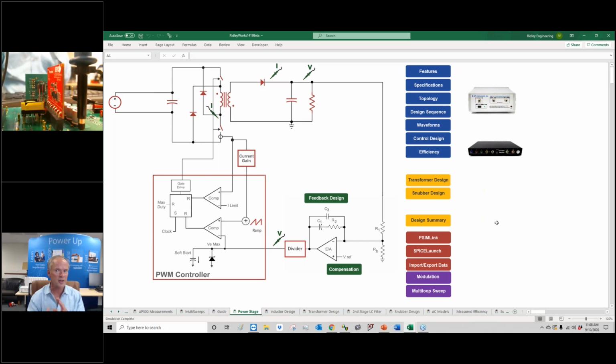All the things we've done on proximity loss, that was originally done for 60 hertz work, for utility work. So Maxwell is Maxwell, and everything Faraday did was the same at 60 hertz as at 200 kilohertz. Just different frequencies, different dimensions, but it all comes out the same in the end. What's that? Different materials. Yeah, you probably wouldn't use a ferrite at low frequencies, because your core losses are going to be less. So you're using laminations of steel, with higher flux density. Yeah. Okay.